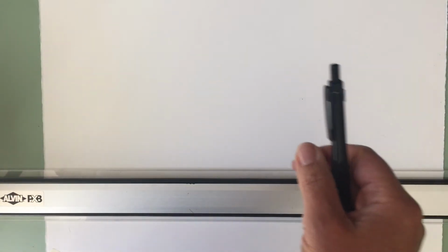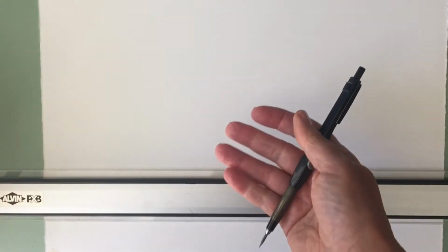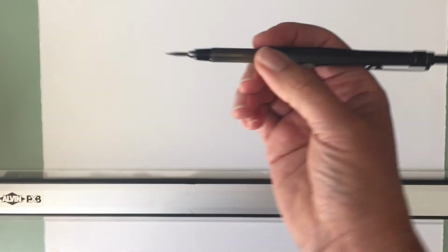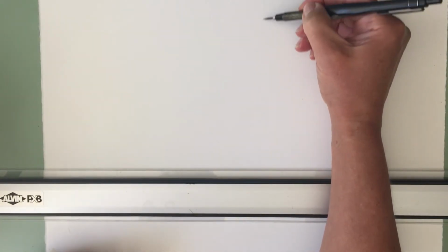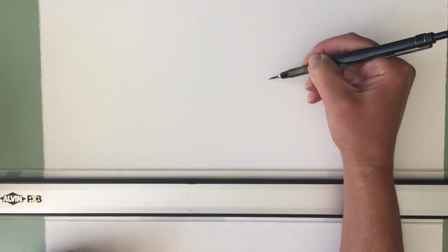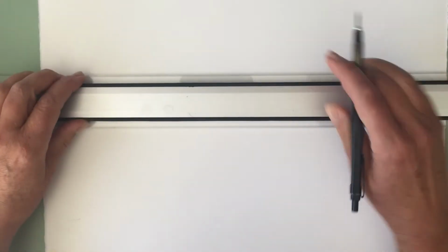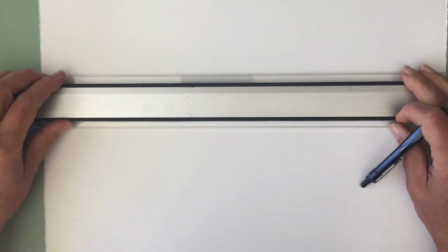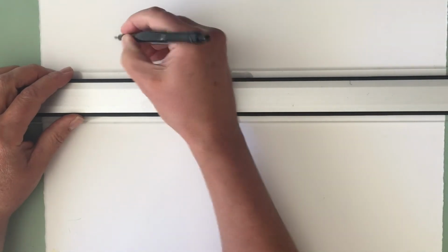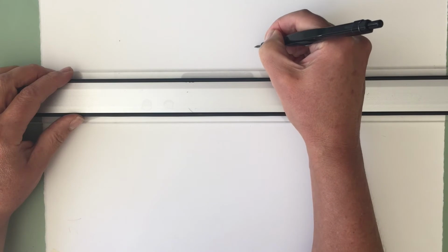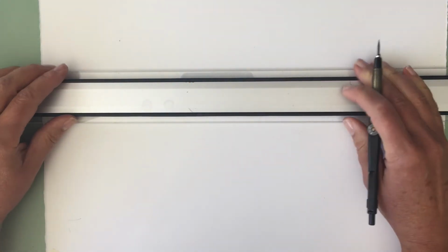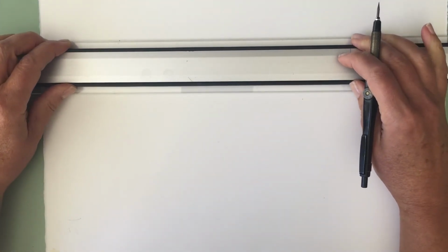Previously, I was using these sorts of pencils to sketch, and that's great for freehand, but now we're drafting, so we are going to use our lead holder. And previously as well, we drew those freehand lines toward us. But now what's regular for us is to draw horizontally. And we want to draw from one point to the other, so you just give yourself a point. And I can't actually say I can go from here to here, because this will dictate the distance I'm going to go, or the direction I'm going to go.